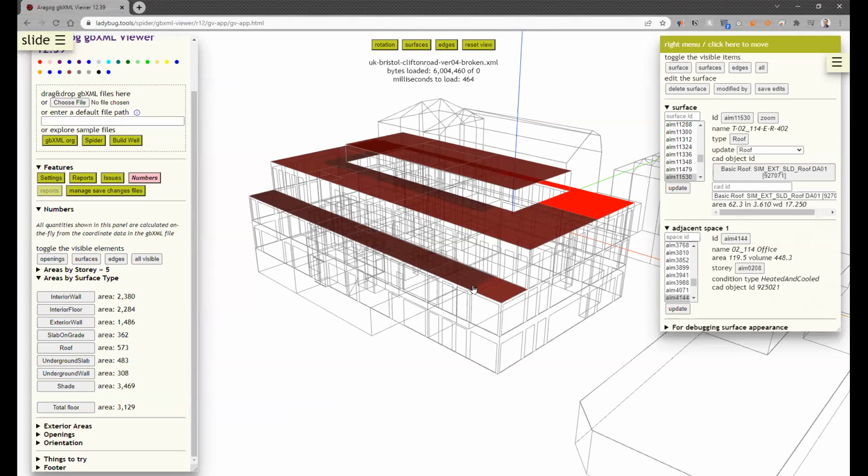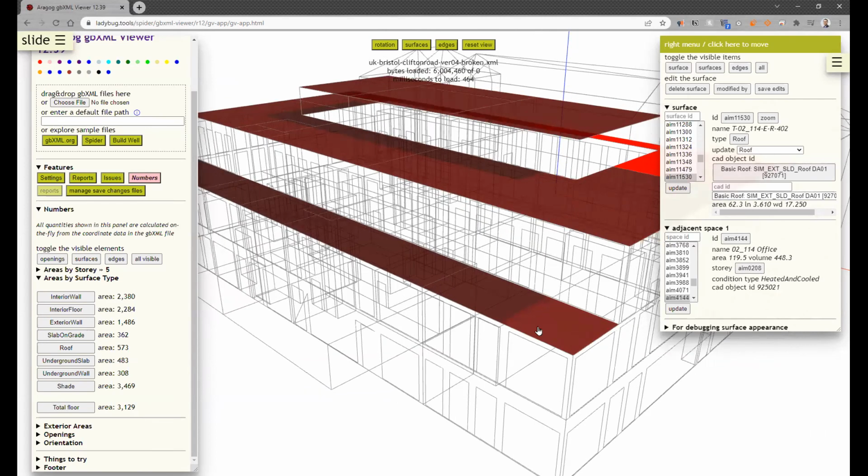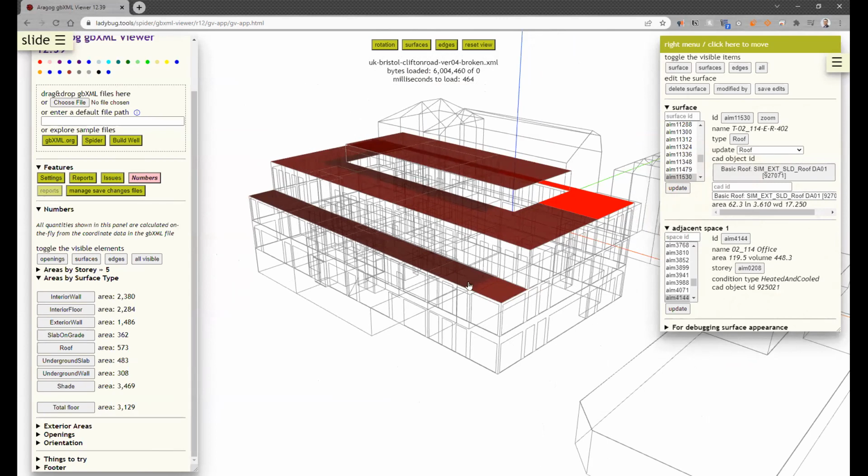Maybe you modeled your roof, and instead of doing the roof at the level, you forgot to set it down the 6 inches that you were talking about, which is a relatively important step because then it's not going to come in as a roof, particularly in your model. So things like that.